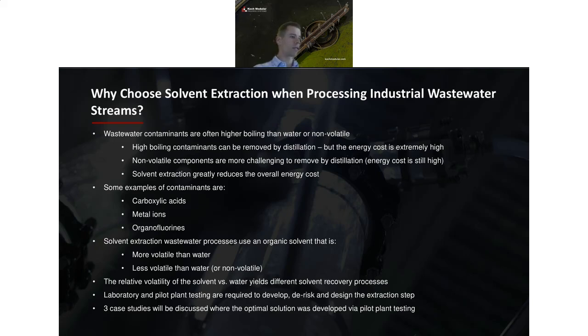I'm going to be going through three case studies today where an optimal overall solvent extraction process was developed through pilot testing. You'll see those different solvent recovery processes, depending on the relative volatility of the solvent versus water, show up in each of those case studies. Just one more thing before I move on. Laboratory and pilot plant testing is required to develop, de-risk, and design the extraction step. Generally speaking, whenever you have an extraction column, you always want to run a pilot test.